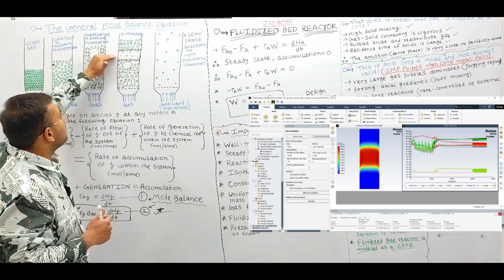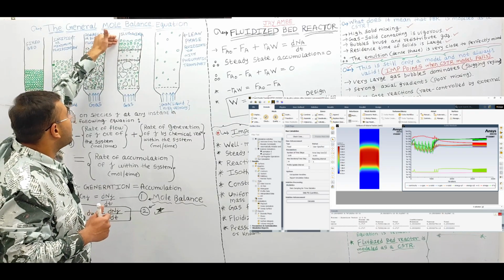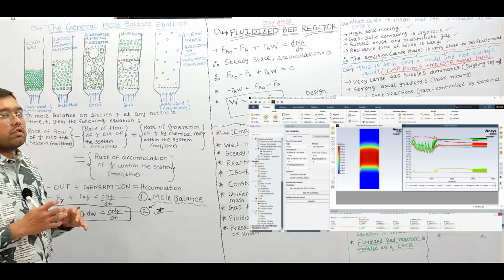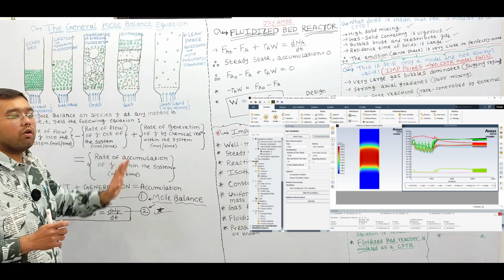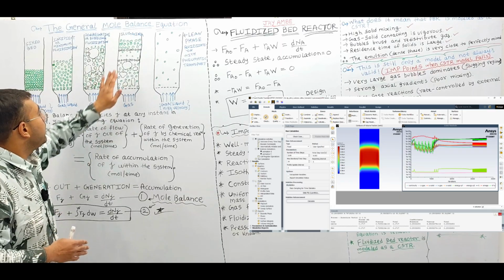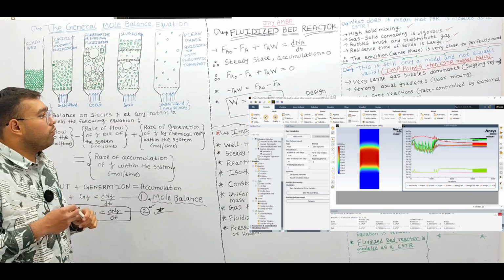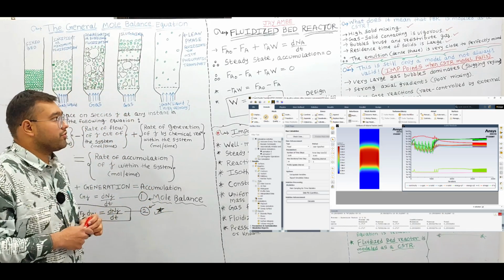We'll have suppression of the solid catalyst particles on the upward side as well as the below side, and due to the formation of this slug, we will not have uniform mixing of the solid and gas in the emulsion phase of the fluidized bed reactor, which results in the slugging regime.